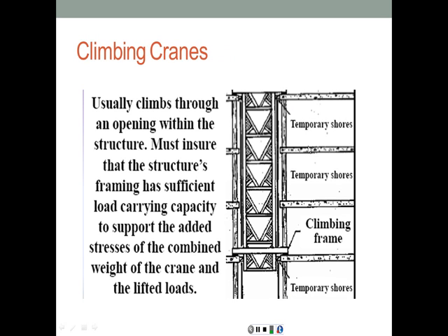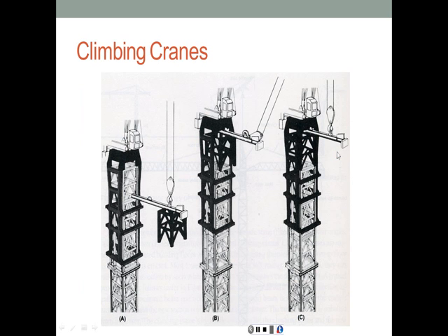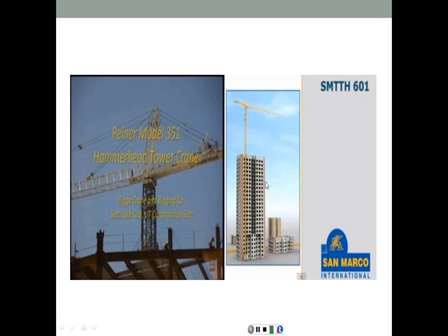We're going to see a short video clip of a model of these cranes being erected. Here we have how the crane lifts itself, how it adds additional joints. And then it slides up to insert this joint, and then once this is done, it moves up, and now the crane is much taller than what it used to be. So let's look at these different video clips that are going to explain how the crane can self-erect and increase its height.